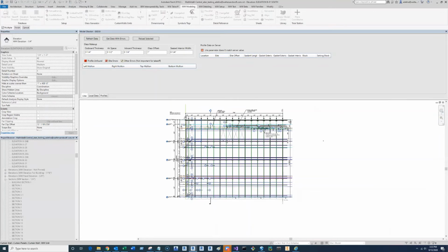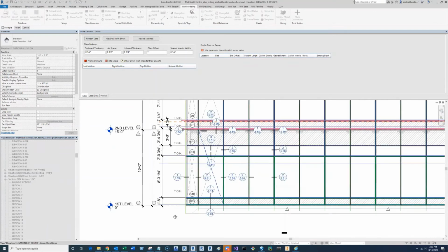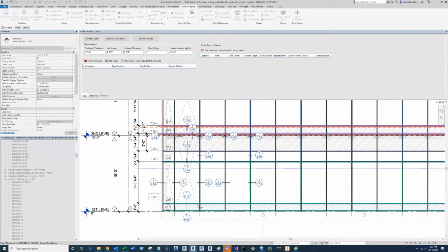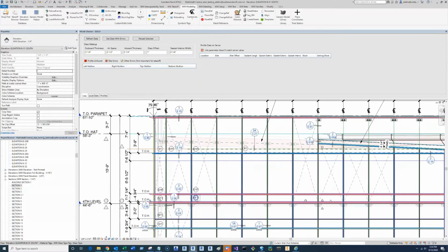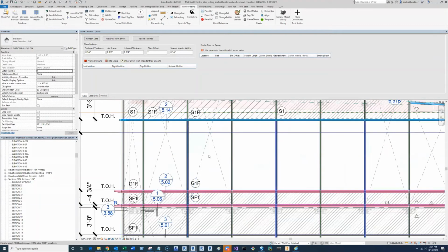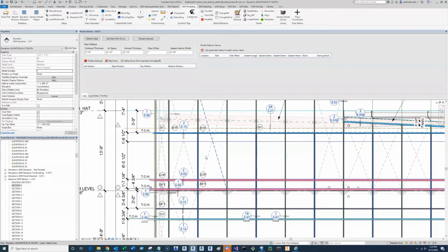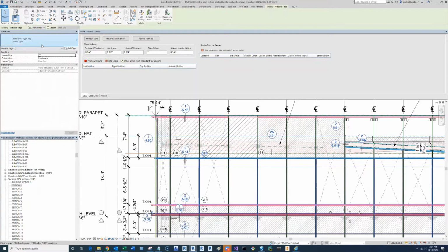So for tags and X, well, they already have X's, but say you wanted to tag an X for whatever reason, you would just select the unit that you want. And then it'll put class tags as well as an X on the unit that you select. It's just a quick little macro, so you don't have to go in and place these manually on all the lights and then draw this.